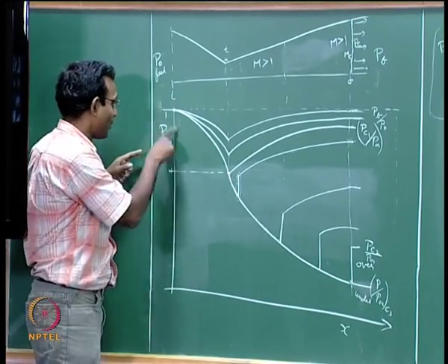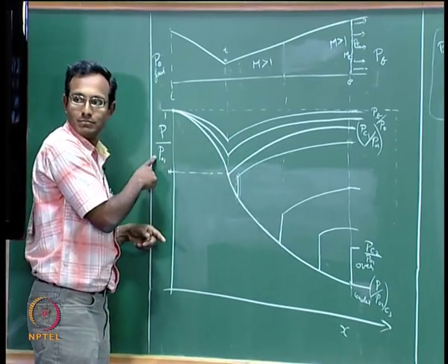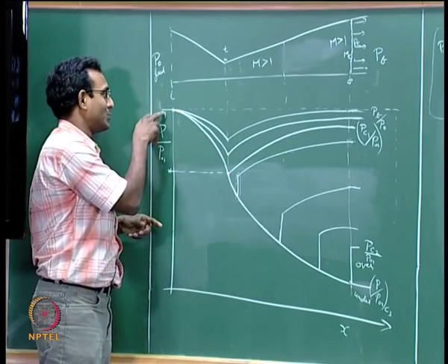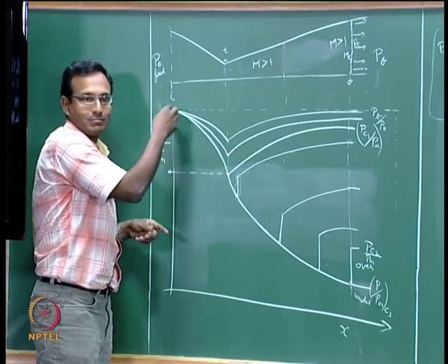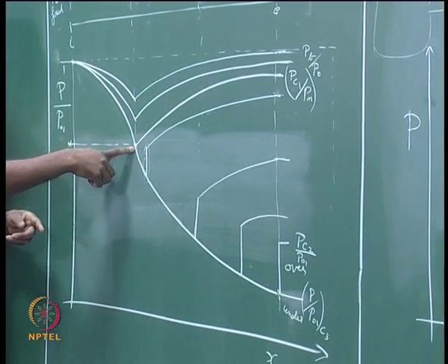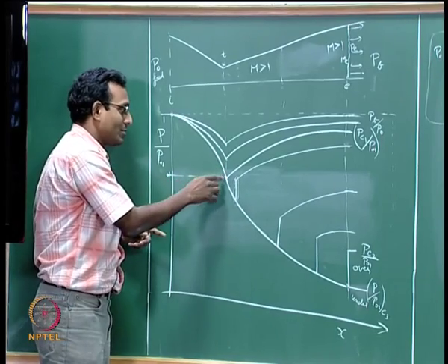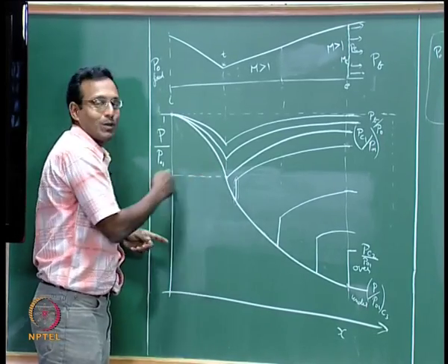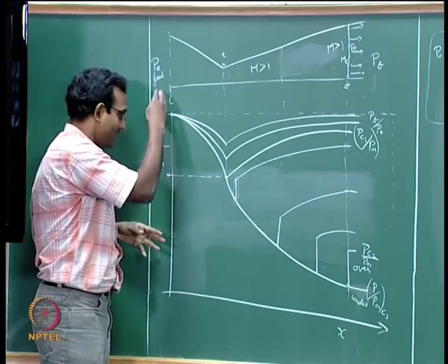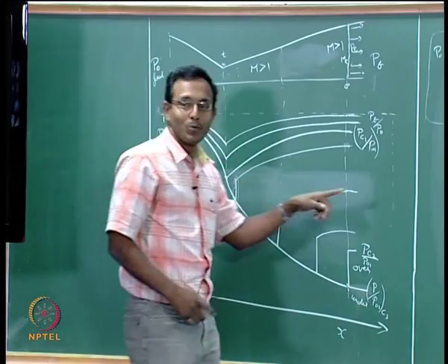If I multiply every point on the plot by a P naught 1, that is just equivalent to multiplying this 1 by a number P naught 1, and similarly if it is say 0.8 P naught 1, 0.5 P naught 1 for gamma, right, gamma equal to 1.4, it is 0.53 something. So, it is going to be 0.53 of P naught 1, that is all, nothing changes, it just scales this plot. That is not the case when I change the denominator.